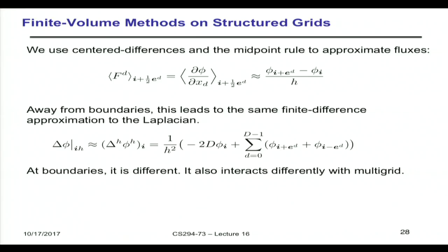But this is representing a gradient on a face instead of just a Laplacian at the center of your stencil. So even though you ended up with the same discretization at second order accuracy, if you went to fourth order, if you did different boundary conditions, if you had a variable coefficient problem where maybe this gradient was multiplied by some conductivity or other thing, then you would end up with different discretizations. But at its root, those things are the same.